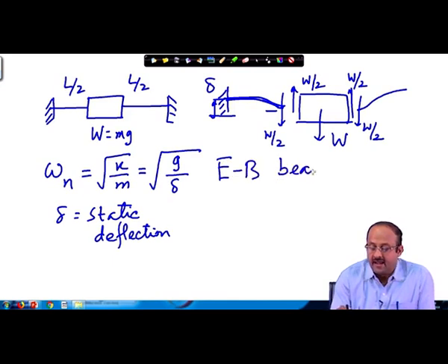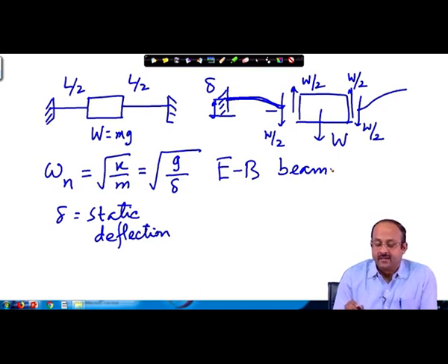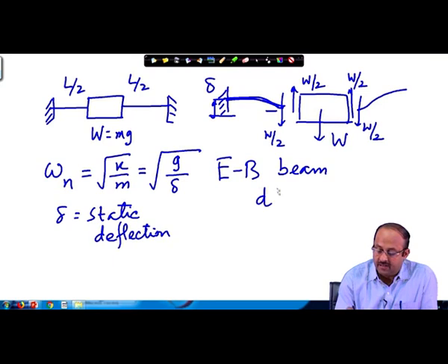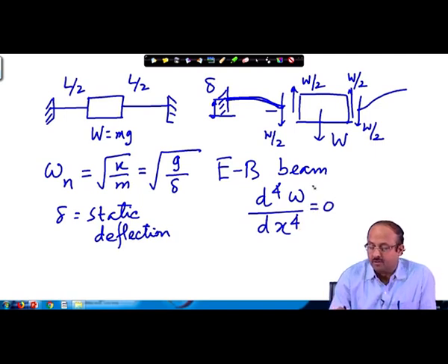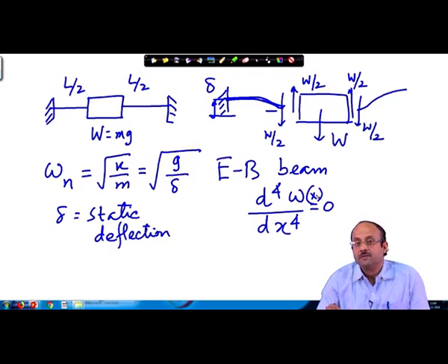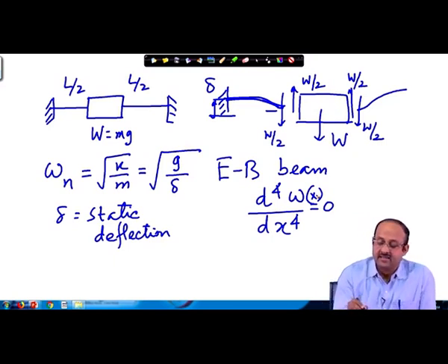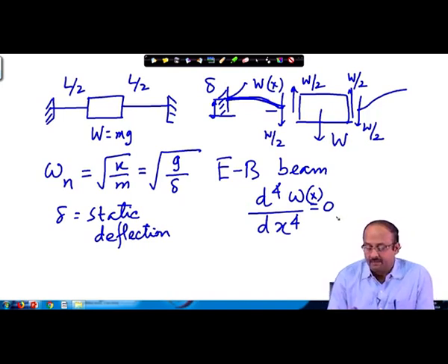Euler-Bernoulli beam theory, and according to Euler-Bernoulli beam theory, the displacement will be according to this form, since there is no other load acting transverse to this beam. Where W is a function of x; do not confuse this W with the frequency of excitation. This W is the displacement of this beam measured in the upward direction. So, we have this, and then the boundary conditions.